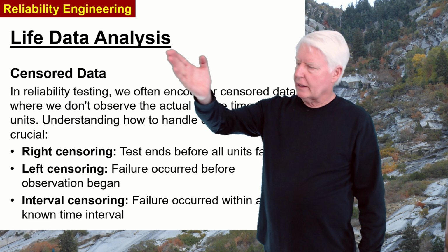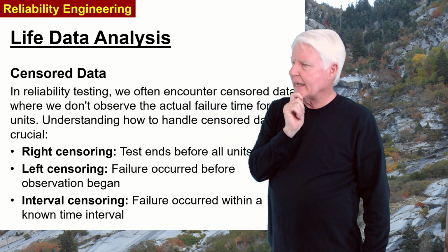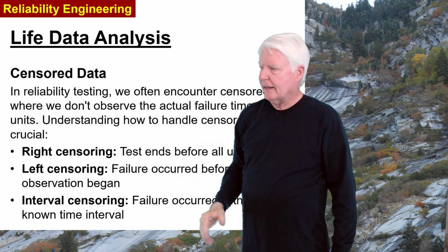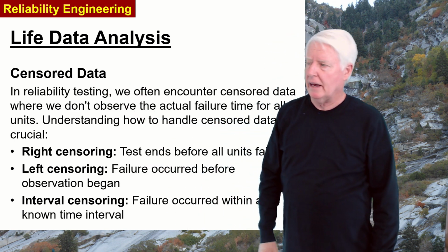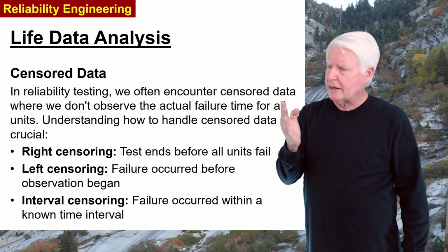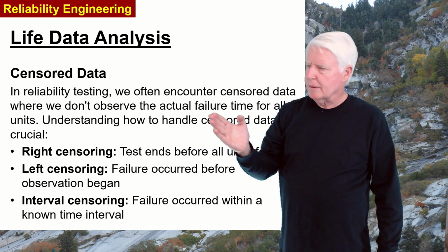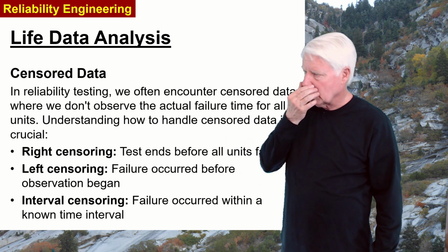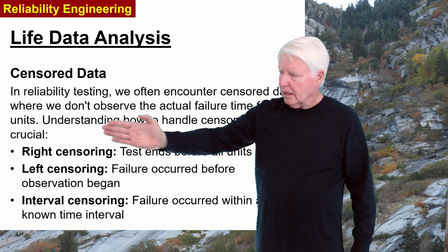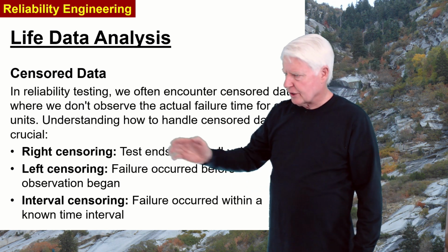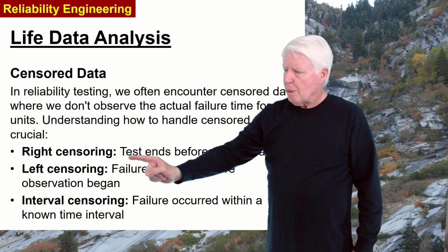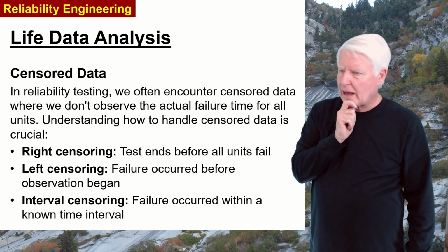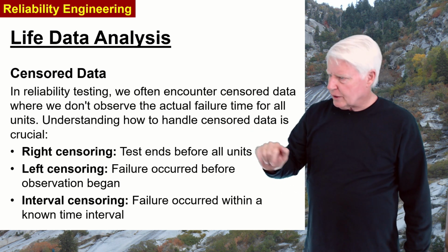All right, another important part of reliability engineering is life data analysis, censored data. That's a very important term, so let's talk about that. In reliability testing, we often encounter censored data where we don't observe the actual failure time for all units. Some of them fail, some don't. Then that would be considered censored data. Understanding how to handle censored data is crucial. Right censored data: the test ends before all the units fail. Well, how do you take all that into account? Well, we teach you how to do that.